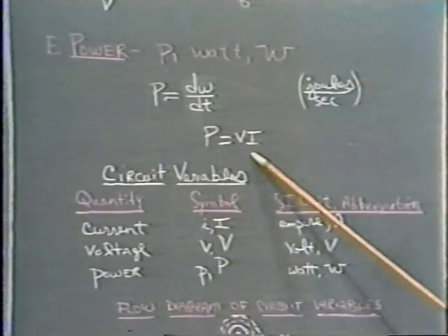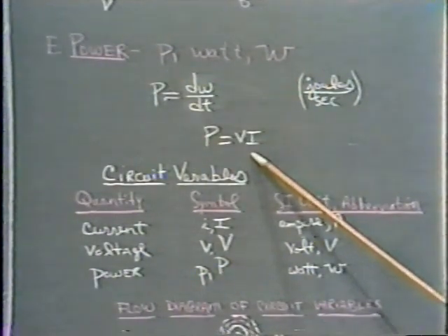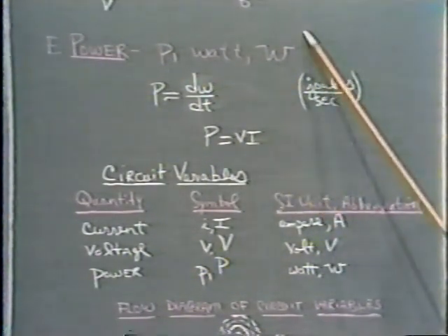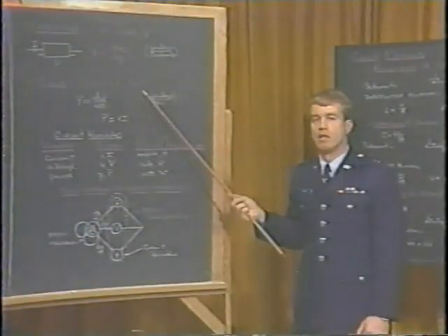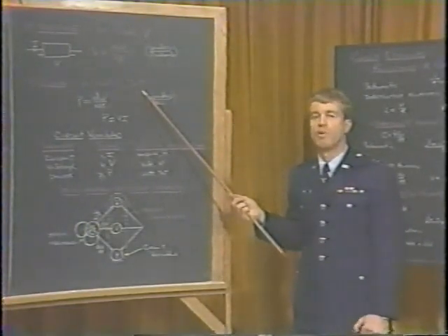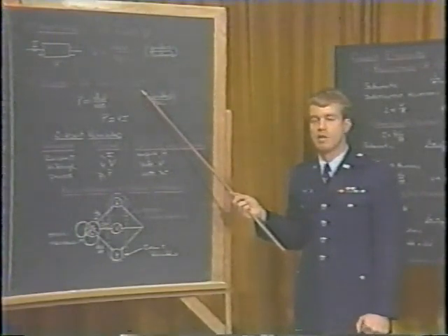And we're referring to the current through the device that is dissipating the power. It's a very critical concept. Voltage always has 2 points associated with it. The point of higher potential and the point of lower potential. Whereas current is a single point concept.